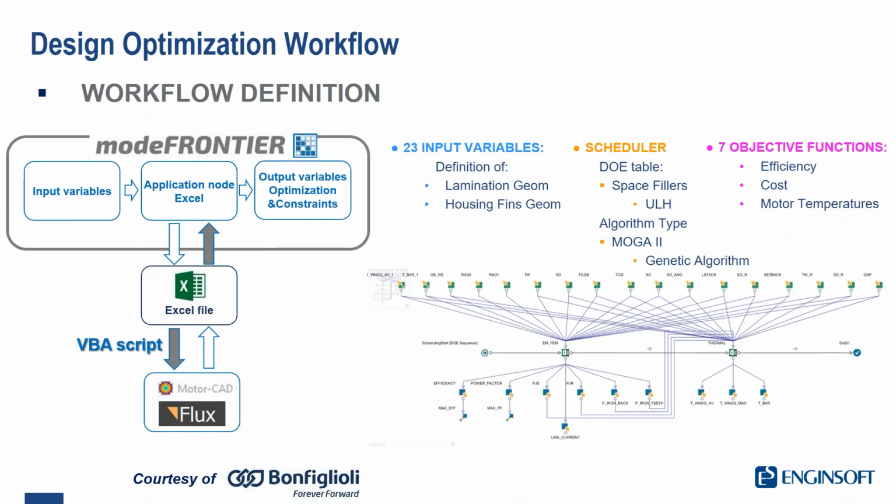After that, a workflow for the optimization process has been built, integrating the typical technologies used by Bonfiglioli in their development process. In this case, Flux for the electromagnetic evaluation and MotorCAD for the thermal management evaluation. Then geometrical information has also been extracted from the workflow to evaluate cost performances. MotorCAD, at the time of the activity, was a standalone product. It's not inside ANSYS Workbench. Otherwise, we can use the ANSYS Workbench direct integration node in order to integrate this product inside modeFRONTIER.